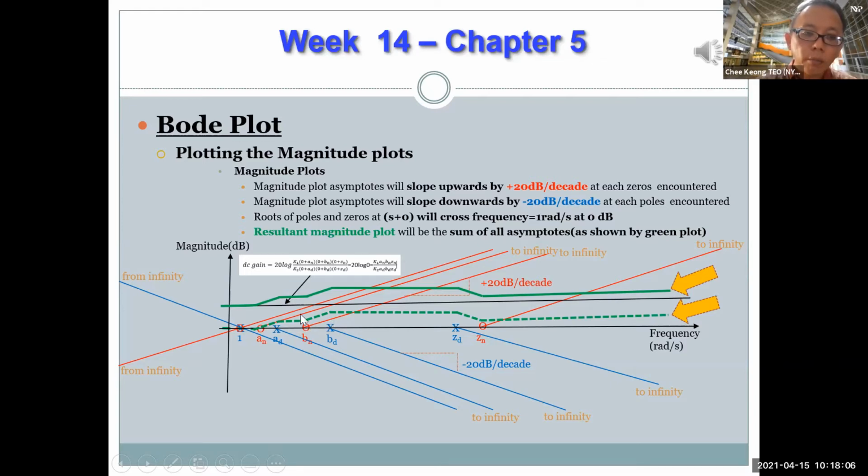additional going up, right? Because the original going up is still going up, because it's to infinity, and then the second going up adds, so it's 2 up, 1 down. So 2 up, 1 down, the net result is 1 up, so it continues to go up. Now at this point, BD, another pole comes up, so it's 2 down, 2 up, right? 2 down, 2 up is flat. So basically it's flat all the way, because there's no more additional pole or 0. Flat all the way, right?